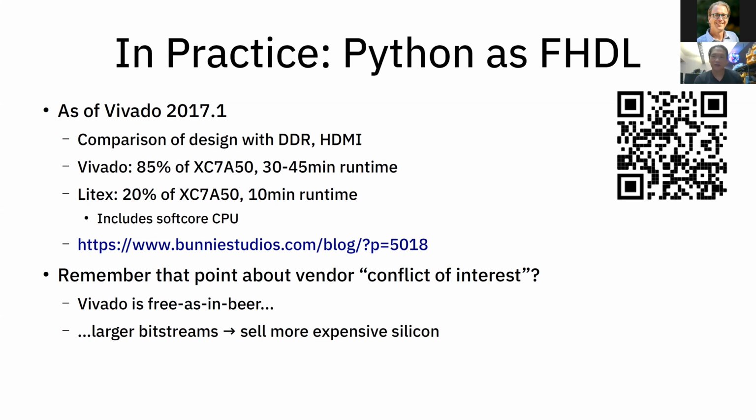It was a pruning exercise, for example, to use a Vivado flow. They had these AXI buses that they're using on the inside, and they would include slave interfaces that you didn't need. They weren't connected to anything, you actually leave them unconnected. And when you dug into the hierarchy of what came out, those slave interfaces were just fully there.